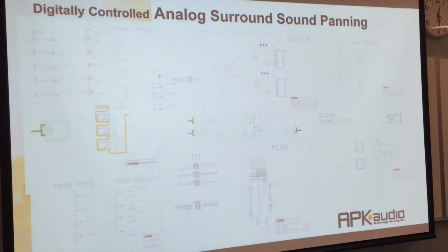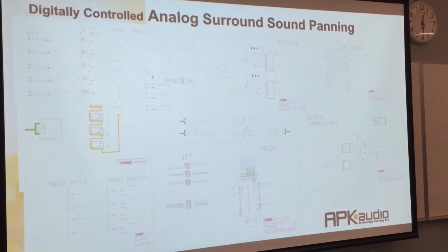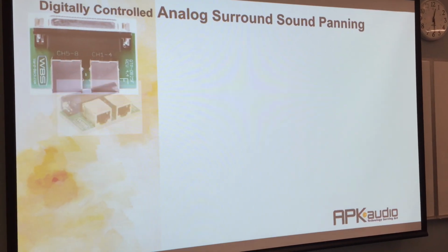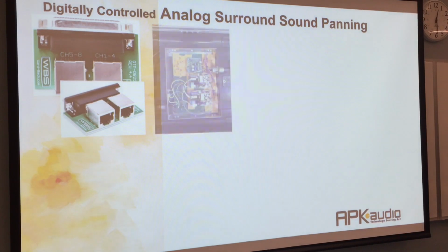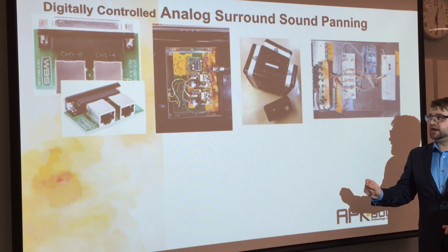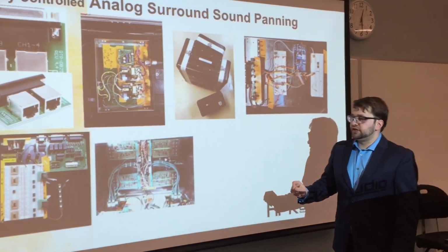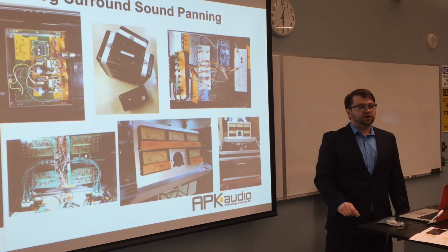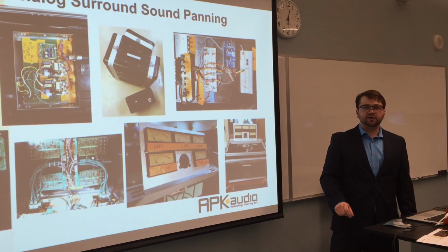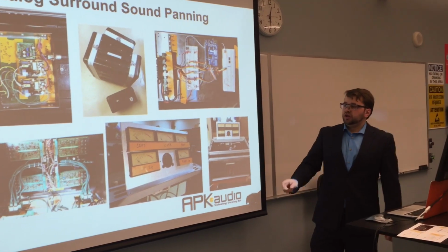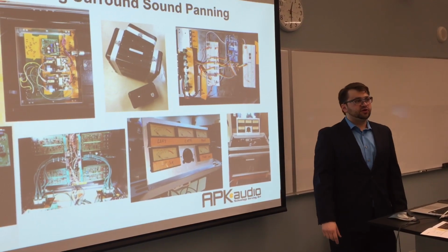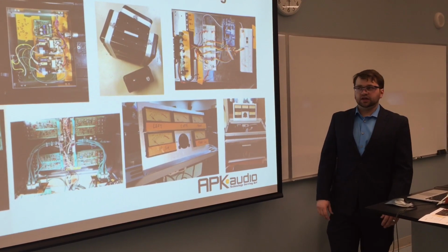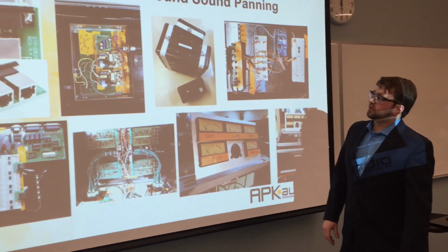I drew and I drew and I drew. I think there's 14 pages of drawings just to make this thing happen. My big thing right now is I exploit quad twisted pair cable, so everything internally is balanced. I use RJ45 connectors as often as I possibly can because they're quick to set up and tear down. Also, the different twist ratios within a piece of cat cable help with crosstalk reduction, so it is just the most ideal cable for audio.